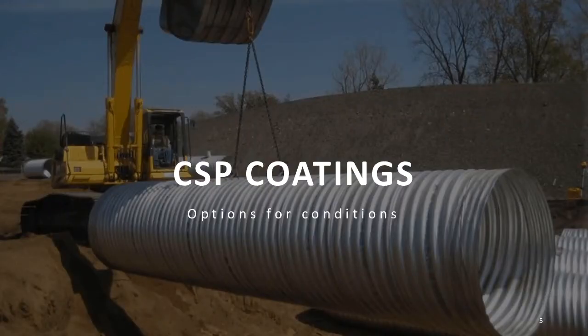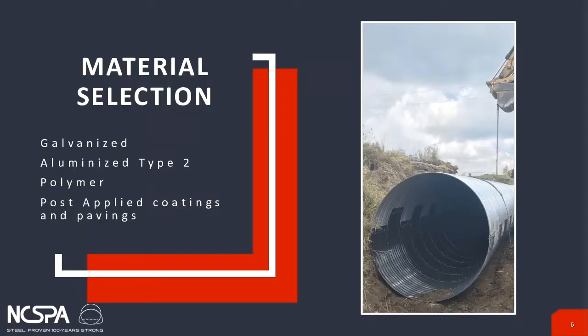As a quick review, on our first webinar, we discussed the types of coatings available for CSP. These coatings include galvanized or zinc coated, aluminized type 2 coated, polymer laminated, and post-pipe fabrication applied coatings and paving such as asphalt coated and concrete lined.